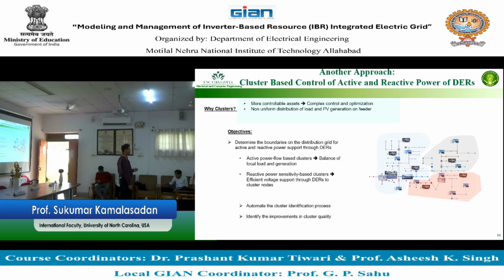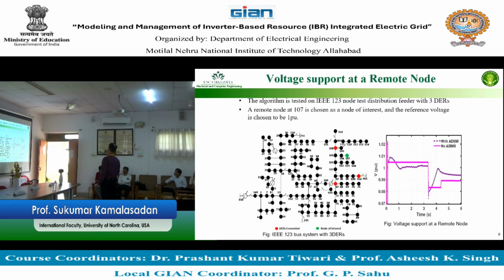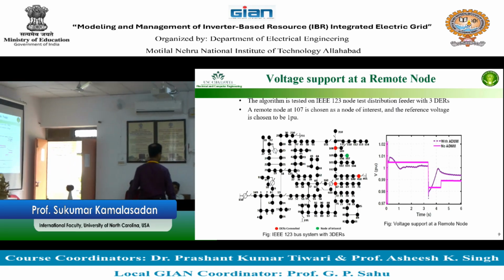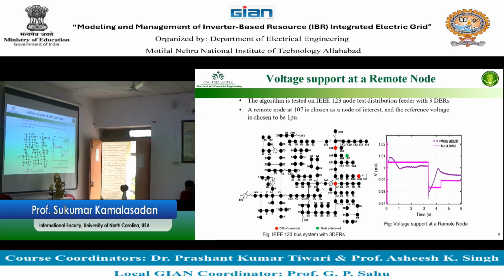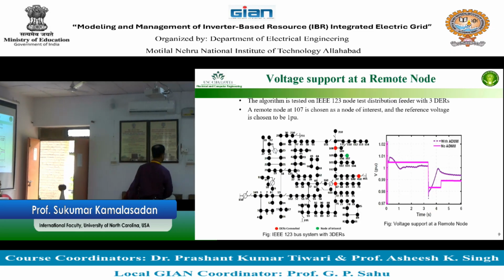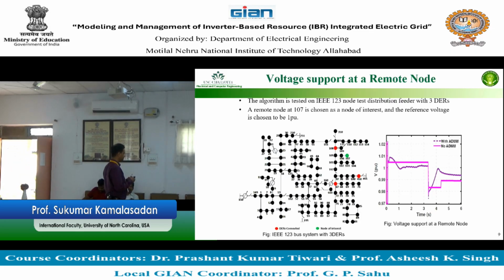Tomorrow we have a session, or maybe even this afternoon, where I will show you how this reactive power can be coordinated with this regulator. So if this reactive power is pushed to control the voltage, this regulator also will be seeing that, right? What's the regulator going to do? Regulator looks at the voltage on the load side and controls the voltage. So regulator is actually looking at this point. So if this DER is pushing reactive power here, this regulator will be looking at that, right? Which means it affects the regulator operation.